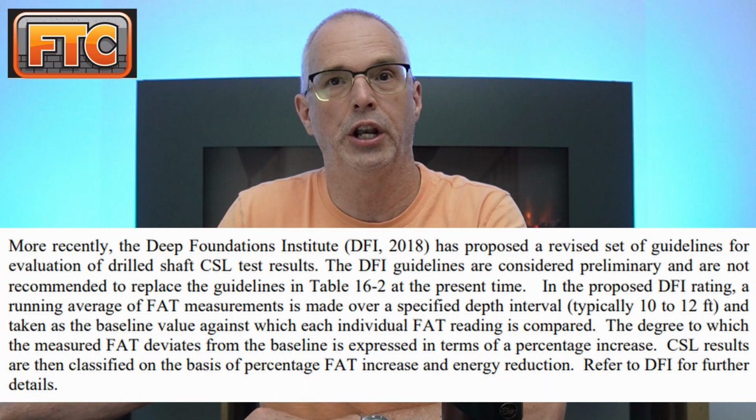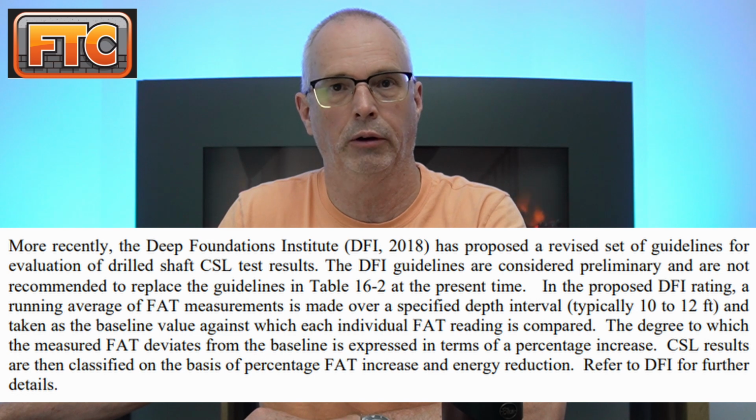DFI also could have provided more details for follow-on investigation methods such as CSL tomography, concrete coring, CSL testing between the core hole and the CSL pipes, and other methods. I provide an overview of these methods in this video. It should also be noted that the Federal Highway Administration Manual considers the DFI guidance to be preliminary and should not be used as a replacement to the conventional concrete condition rating criteria.